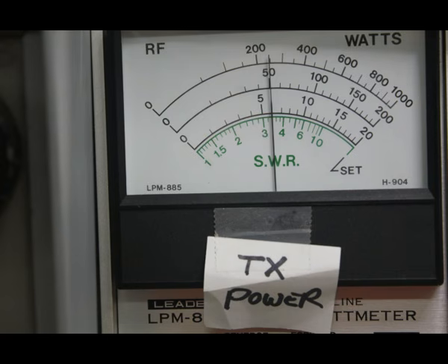But when you look at these two numbers, if you subtract them, you pretty much will get someplace around the true load power. So if we take 15 watts from the 19 watts of forward power, we see that we should have someplace around 4 watts being delivered into the load meter, because that's what the HM2140 is telling us.